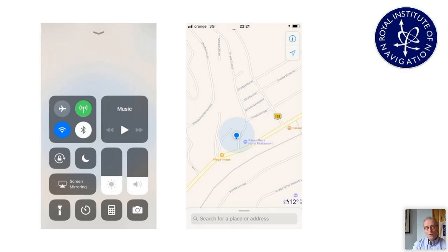Wi-Fi positioning is an interesting topic, actually, and I won't go into detail, but there are some big improvements coming where Wi-Fi positioning will actually measure the round trip time rather than just the power level from the different access points. And that can bring this inaccuracy much tighter, perhaps in the next 3 to 5 years, I think.